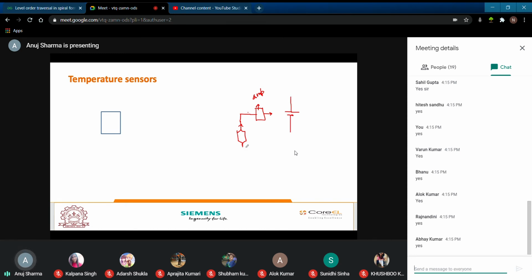For a thermocouple, you got a voltage, you got an amplifier. That amplified value has been fed into the current loop, which was something like this. It has its resistance, which will always be in series. We have a particular receiver, which has its own resistance added in series, and you have an I. So from a thermocouple, due to temperature difference, you get a current or voltage.